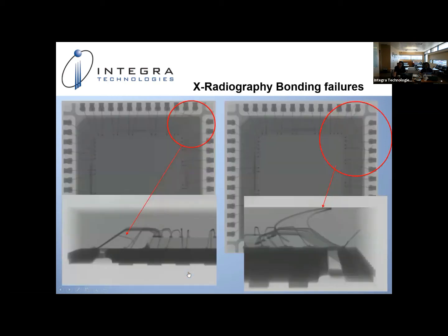All right. Well, here's a good reason. During electrical testing, we experienced several failures. Using X-ray, we were able to detect broken or misplaced bond wires, as well as extraneous bond wire material. On the left-hand image, on the top side, the bond wire is not connected at all.